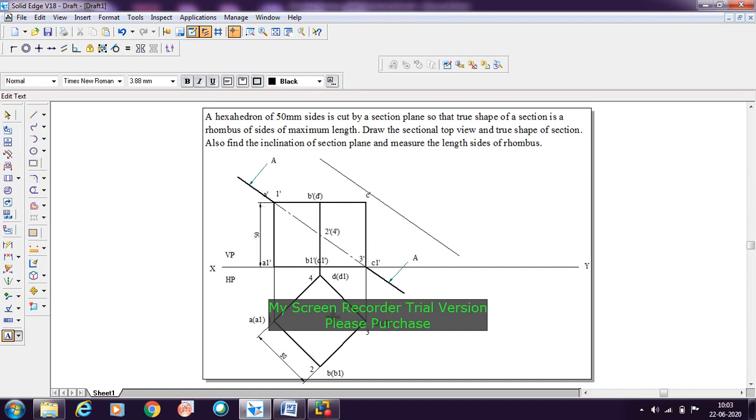When you cut it here, the simple concept is where and all it is cutting. So you need to identify the points in the top view. Once it is identified, it is covering the whole top view here, because it is cutting all the corners containing the points in the top view. So for that, now you need to show the hatching here. It is because this is the cut portion.